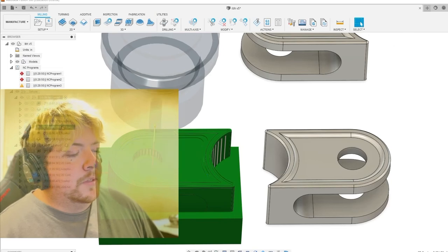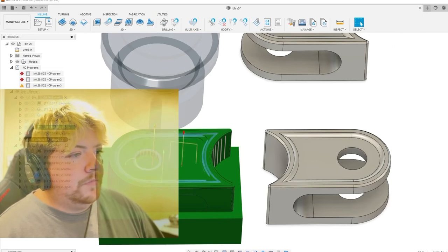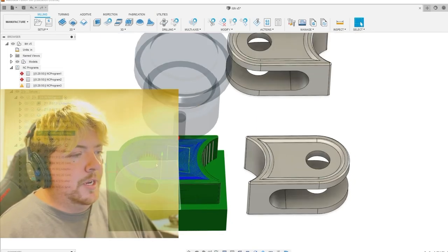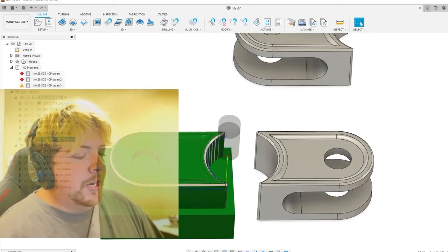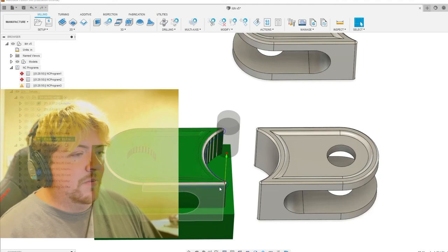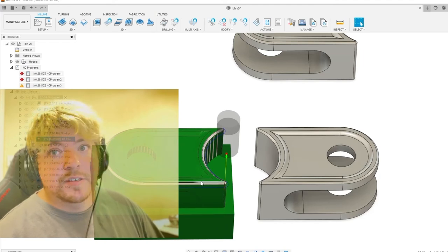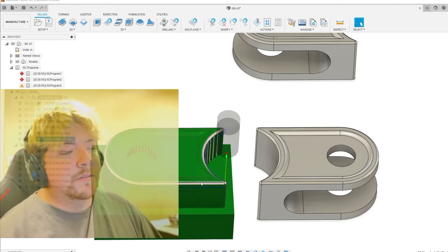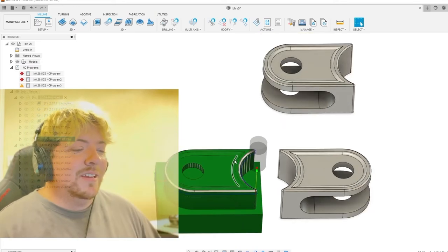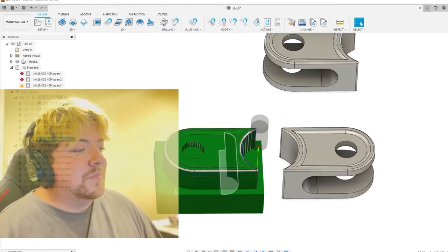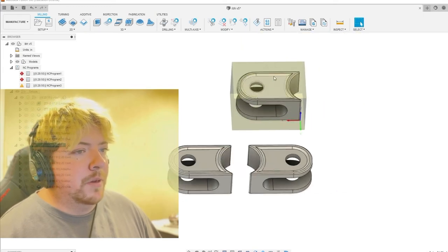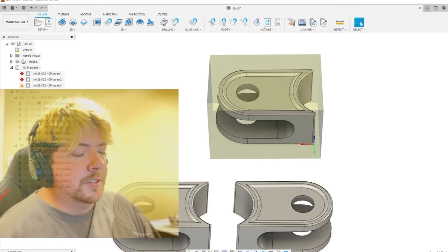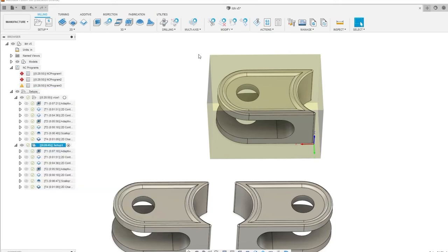And then a contour, a scallop, which is a 5/16 ball, and then a chamfer, which I think I'm using a 1/2 inch spot drill, which I should probably be using a chamfer mill, but whatever, it works. And then this setup, I think it's pretty much the exact same thing, just different geometry selected.